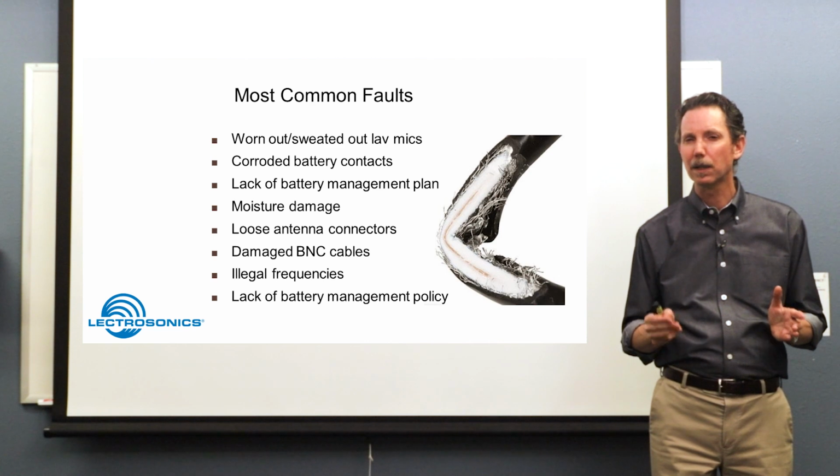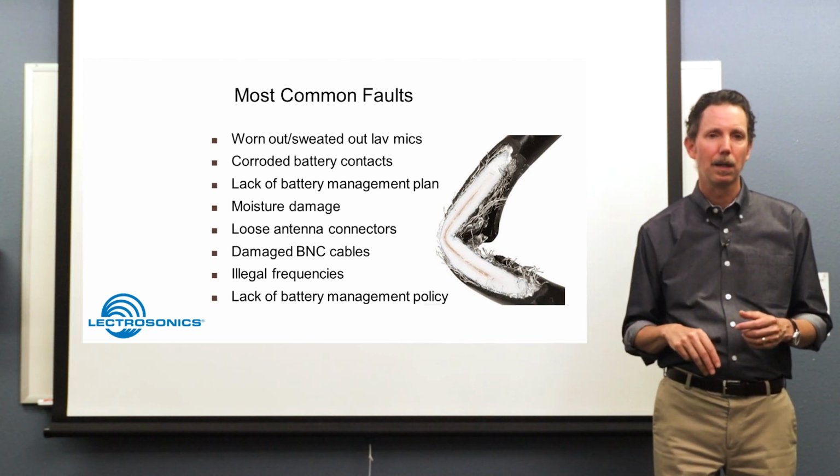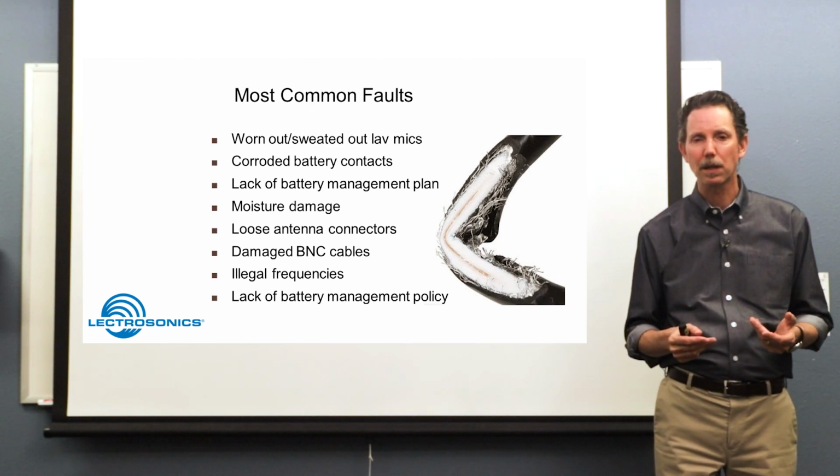Professional type nickel metal hydride AA batteries, they'll say they can be charged 500 times, and that would be once a day for more than a year. But I find that that's a little bit ambitious. Most of the time, replacing them once or twice a year would be a good idea to make sure that the batteries that you have are going to last as long as you expect them to in your wireless transmitters.